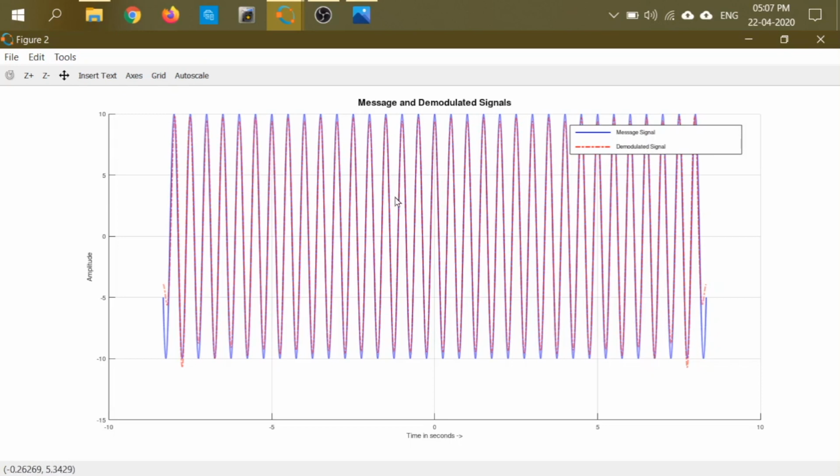This red signal is also adjusted for bias and amplitude variation. We applied an amplifier up by a factor of 60 there, and for removing the bias we subtracted the mean value of that signal from itself. So it is matching perfectly with this, but otherwise also it is okay, right? Now this was for the case of tone demodulation. By tone demodulation, we mean that the modulating signal to begin with was a sinusoidal signal.